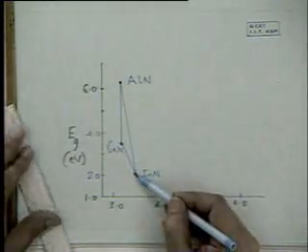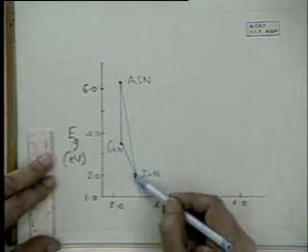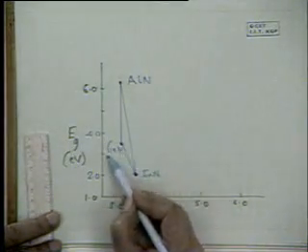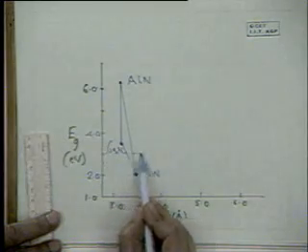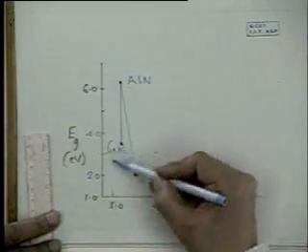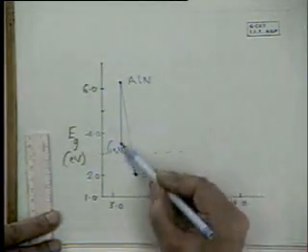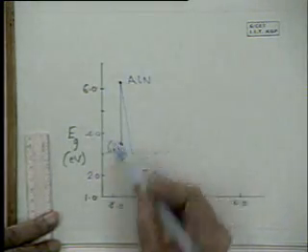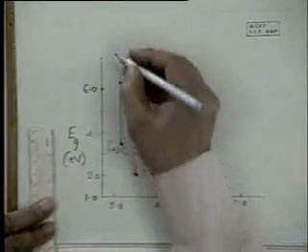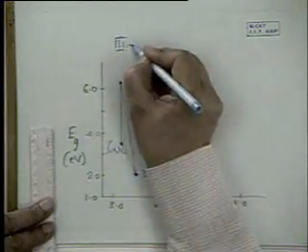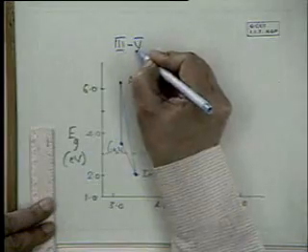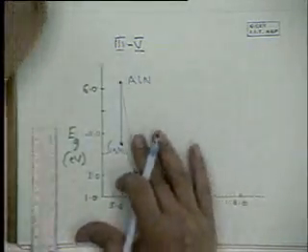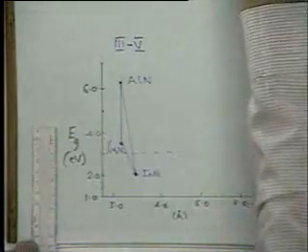And in fact, we are not interested in 2 eV because we already have gallium phosphide here. So we are really interested above this, probably in this region above 3 eV. So above 3 eV, we can have just a little bit of indium in gallium nitride, or this whole series. So these are the III-V nitrides which are important, and I'm emphasizing this because these are direct gaps, so they're at the basis of the new blue emitting laser materials.